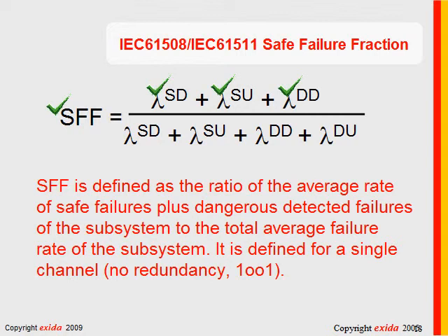There was a comment. I saw a draft of the new 61511. It appears transmitters are now considered Type A devices. Do you consider transmitters always fail in a deterministic manner? Oh, no.